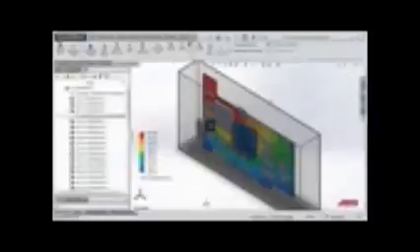Once everything is set up, we'll want to start looking at our simulation. To run the simulation, click Solver, Solve. On the bottom left in FloTHERM XT, click on Thermal Analysis. The Goals dialog will open. Convergence goals are values chosen by the user to follow the behavior of the components and help the simulation converge to a steady-state solution.